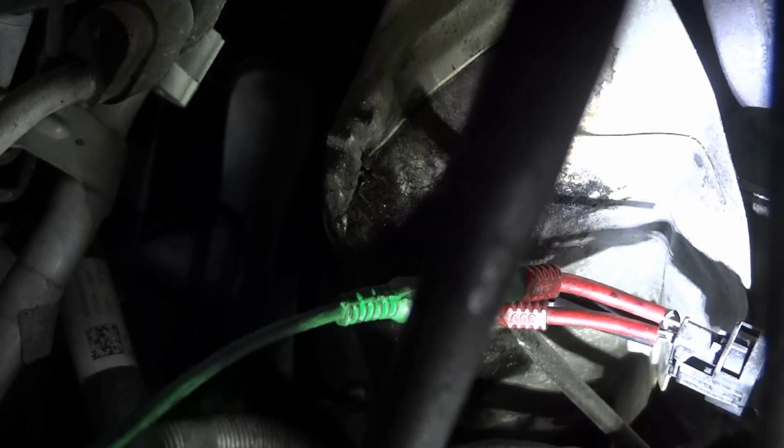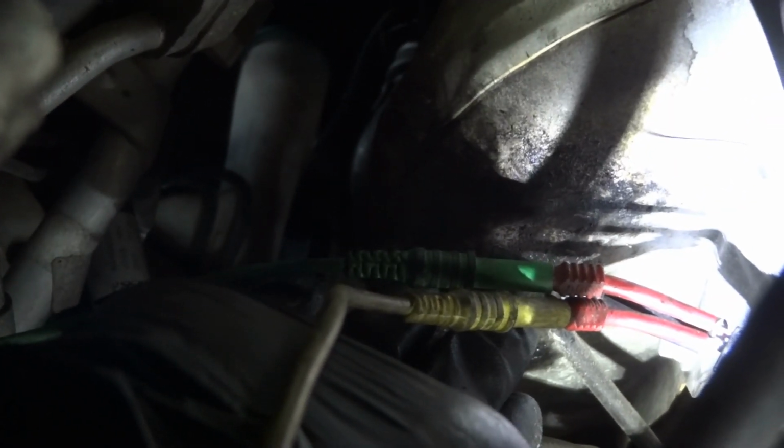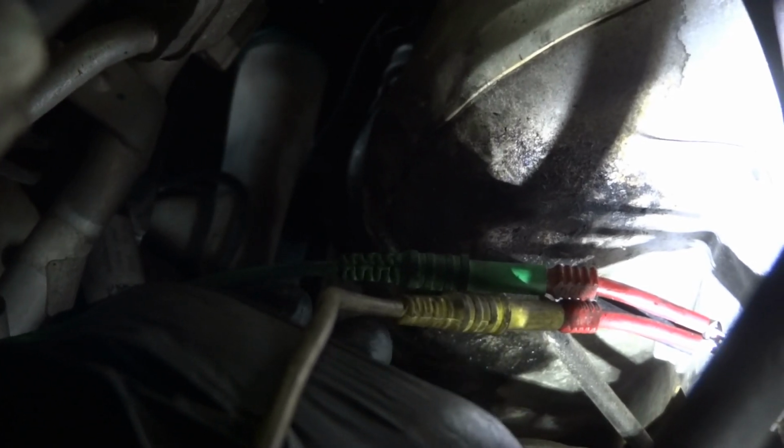So now the second one, I'm gonna connect this one to the yellow test lead. Now, I don't really care what wire is what at this point. I mean, this is a pretty simple circuit. It's a Hall effect sensor, so one is gonna be 5 volt, the other one will be the signal, and the third one will be ground. So we know that already.